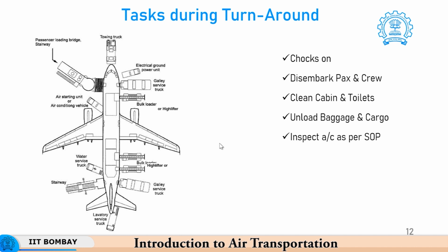Then we look at nitrogen bottles, we look at the landing gear, we inspect these things visually. So, you will see some engineers going around the aircraft with a torch, and sometimes even the pilots are qualified and trained to do this kind of observation of the aircraft between two flights.